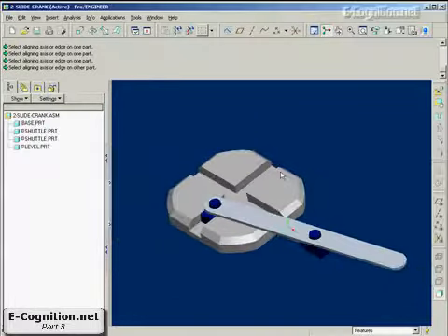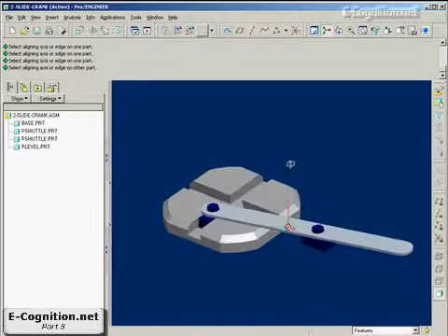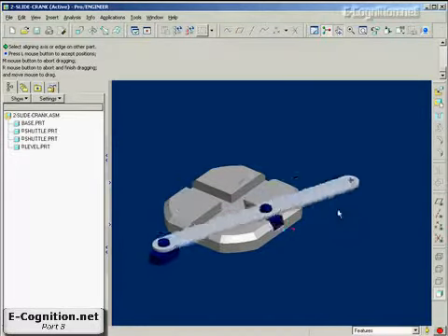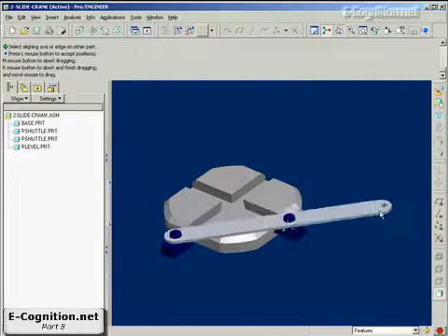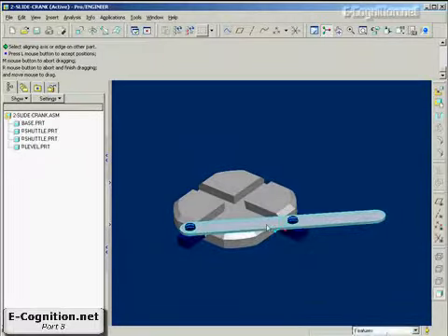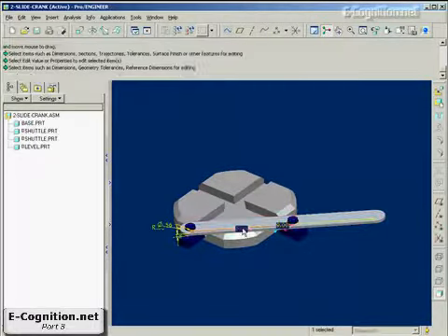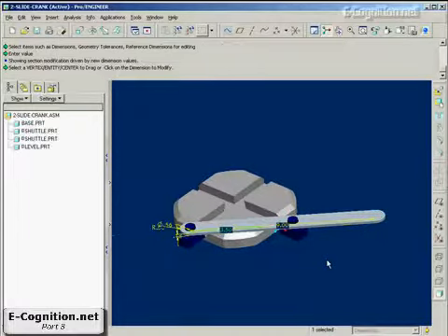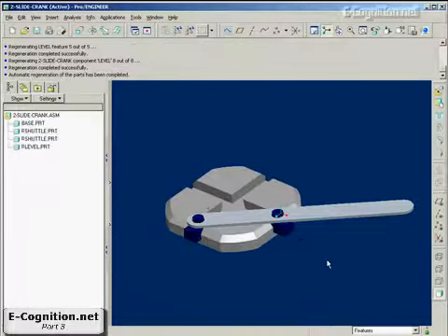Oh, so we got a few problems here, but it's starting to shape up pretty good. If I grab now the end of our handle, you see it's starting to behave just like we hoped it would. Let's take a look then at features. Go back into here and change this. Instead of 5 apart, let's make it 3.5. Control G. Aha, that's starting to look a little better.